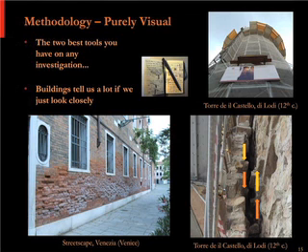Could almost be any building in Venice, but the thing you can really notice here is that down very low, you can see the brick above the travertine water table. Those brick are intact, and they're pretty much wet all the time. Up above, say mid-height or upper part of those windows, those brick are intact too. So the brick that are always wet and the brick that are always dry are intact.